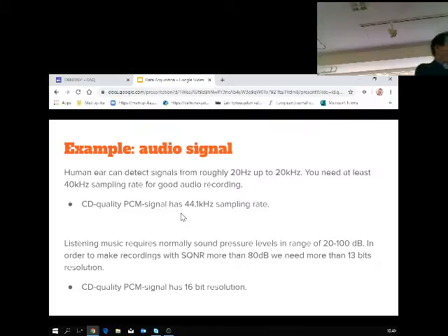And basically because of some nasty features of the Sigma Delta DAC converters, they require those 24 bits in order to have a good audio quality. But the Sigma Delta, the type of DAC converter, is quite nice actually for that purpose.